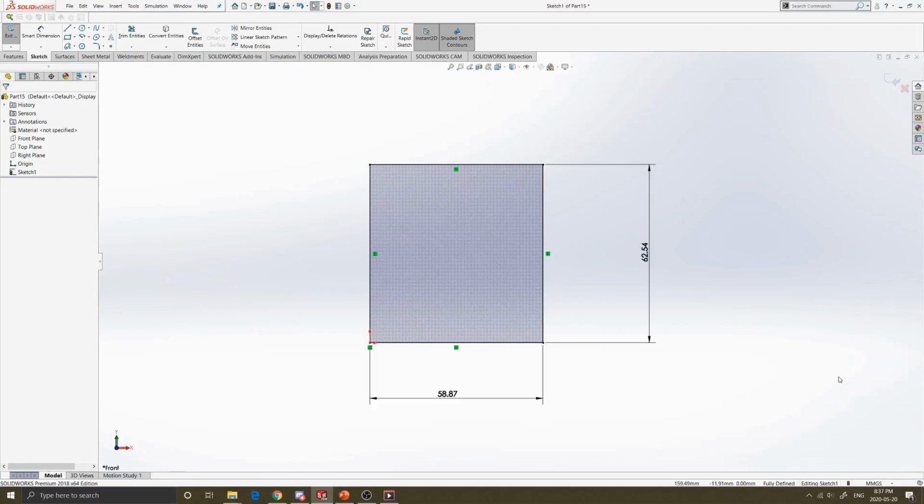So when you want to design something using sketch patterns, it's important to start thinking about how you want to define your object. A good goal that I like to keep in mind is to try to use as few smart dimensions as you can, and try to use more of the line properties and line relations with one another. This causes you to really think about what you need to define about your object, and how these smart dimensions and how you change them will affect your overall design.